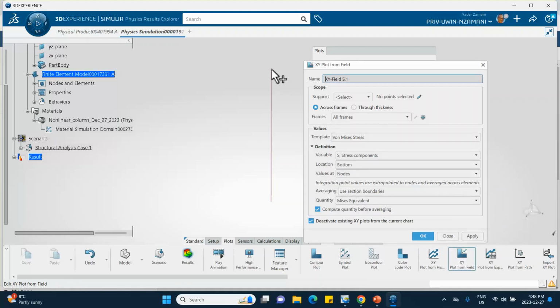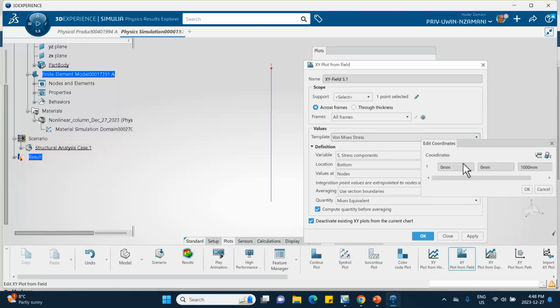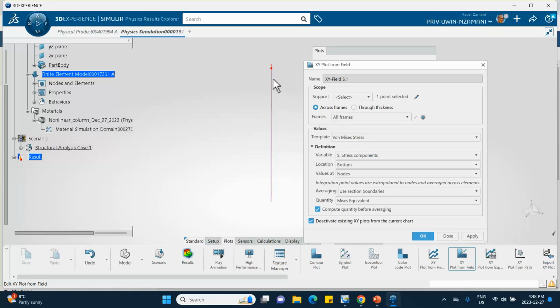Select this point, and if you're not sure what point you pick, you can always click on this and it gives you the coordinates, which is exactly what I want. The only reason I deactivated the graph, the displacement, is because sometimes you pick something, and it looks like it's the point that you want, but it actually will not be the same point.